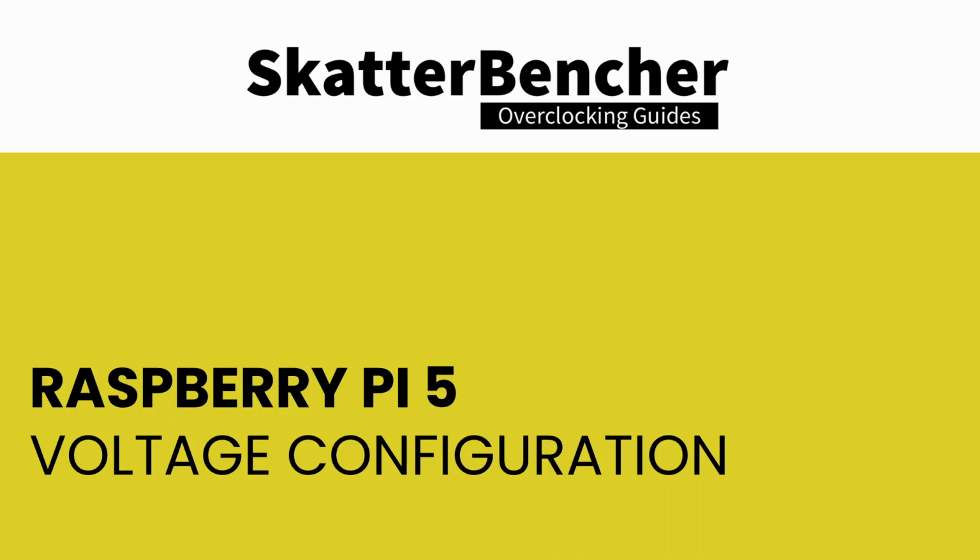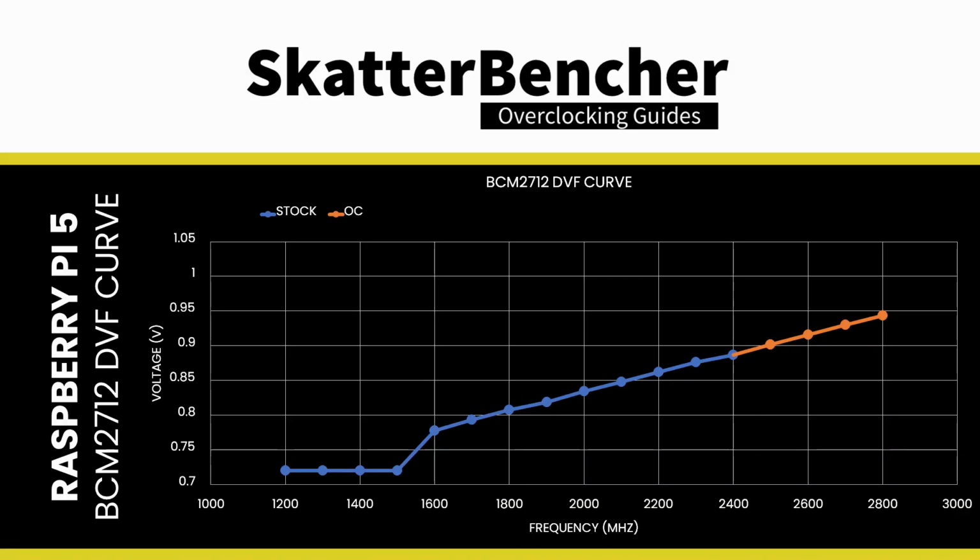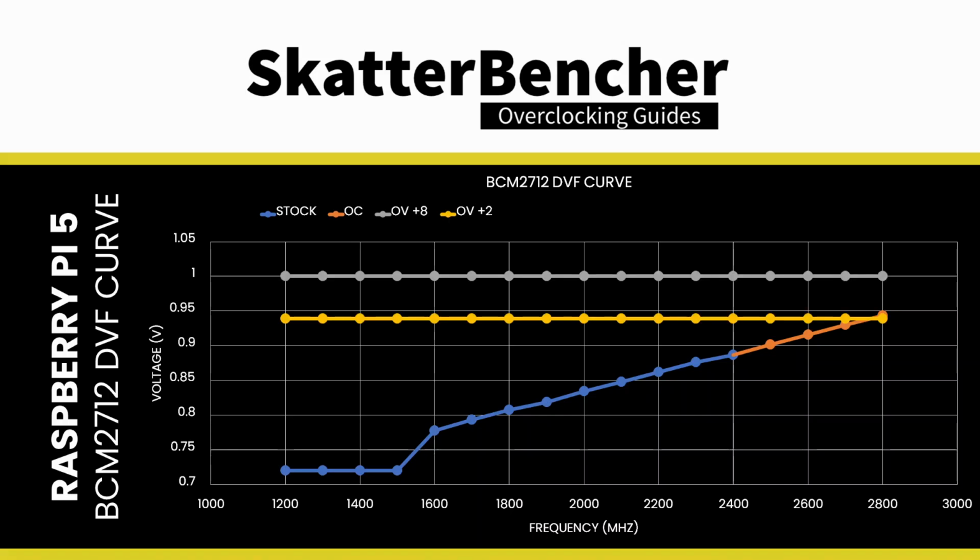The Raspberry Pi 5 offers 2 ways to manually adjust the voltage. An option called overvoltage and another option called overvoltage delta. Overvoltage is the traditional method of setting the voltage, as it simply sets a fixed voltage. The overvoltage parameter ranges from -16 to +8, where +8 sets the voltage to 1 volt. I could only undervolt to -5, which sets the operating voltage to 760 mV.